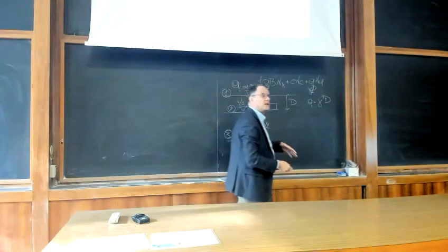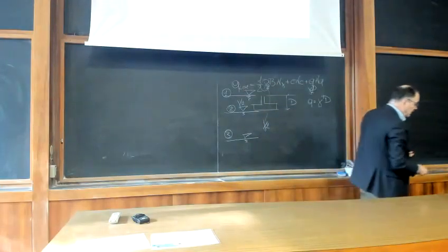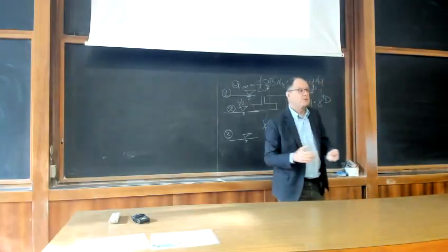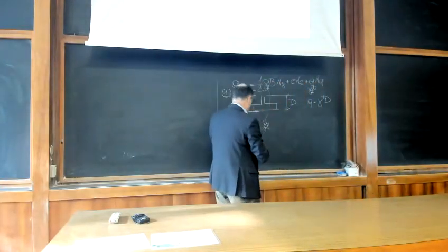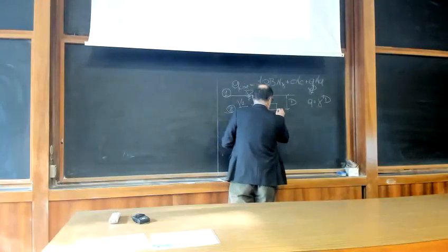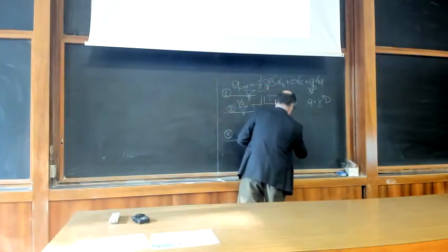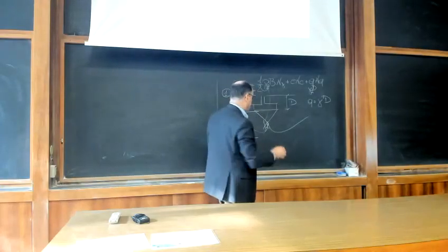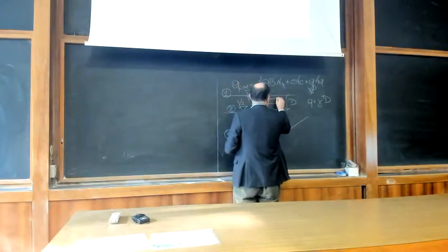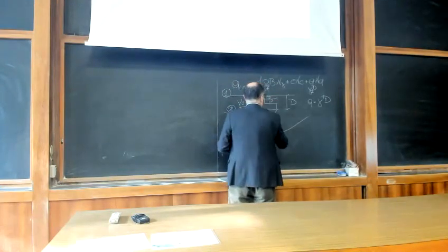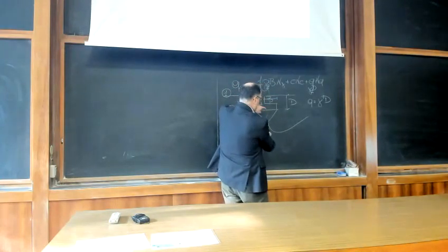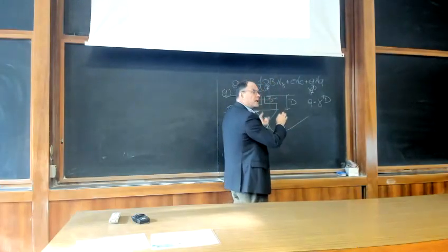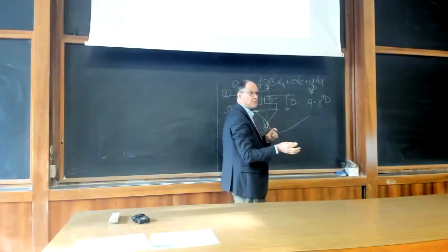Well below the effect of your possible slip surface, your failure mechanism. Now, if we superimpose our failure mechanism, this is probably more or less the size. We know the size of this footing, of this failure mechanism. If you have, this is B, this is typically the depth of the mechanism is about between B and 2 times B.